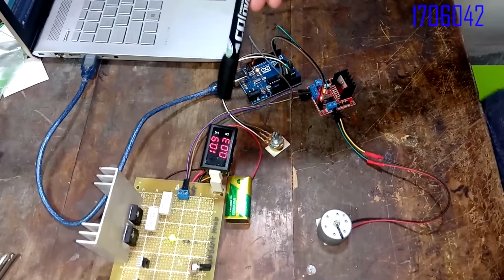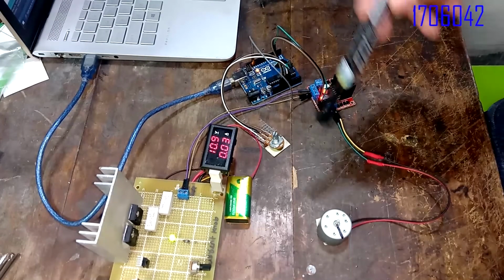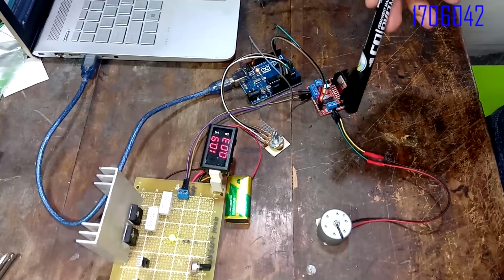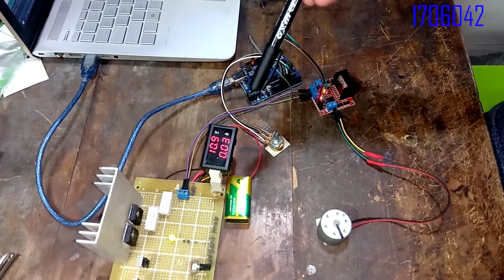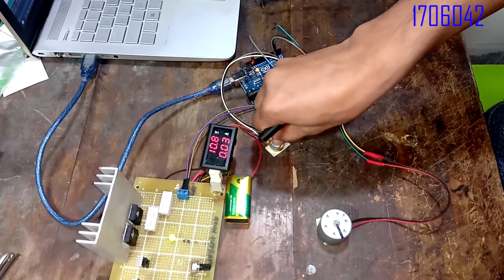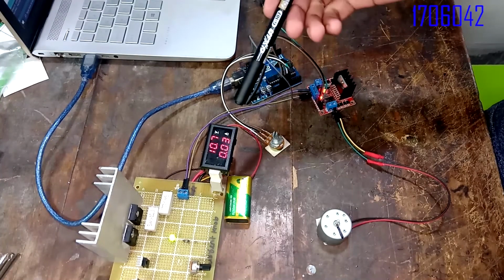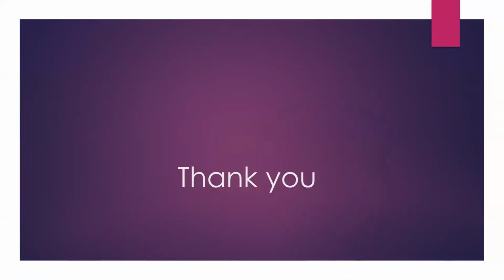Lastly, we will show that our output voltage remains almost constant in case we use a variable load. Here we will implement a variable load using a DC motor, Arduino, and a motor driver. We will change the speed of the motor using this knob, and we will show that our output voltage remains almost unchanged. Now if we increase the speed of the motor to the maximum, we can see that our output voltage changes from 10.9 to 10.7 volt, so we can say that the change in the output voltage is almost negligible. So in conclusion, we can say that our model is working properly and the constraints needed for output have been met.